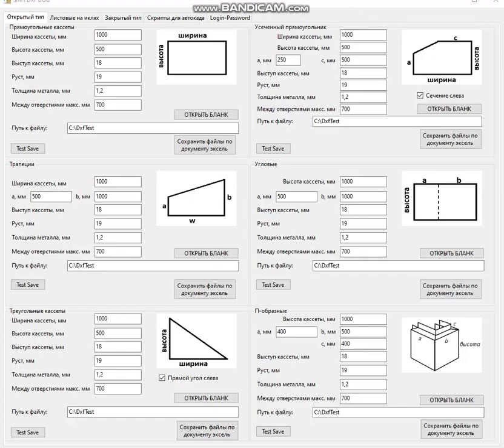With this simple piece of software, let's make a simple drawing for one rectangular panel, width of 1000 mm and height of 500 mm. The thickness of the metal sheet is 1.2 mm and the other parameters are just the bending angles.